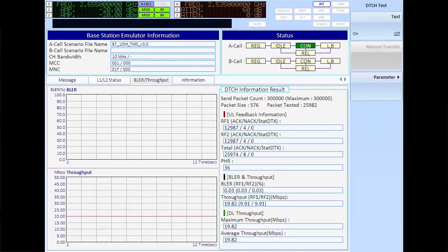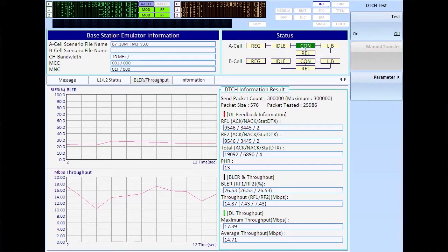The favored metric for determining if a MIMO device is good or not is throughput. With our existing call parameters set up on the PXT, the maximum throughput of this device is 19.82 megabits per second. We've lowered the cell power to a level where we are beginning to see some impact of the receiver sensitivity. As you can see, our throughput is slightly below the maximum rate. Now let's see what happens to our throughput rates when we start rotating the antenna pattern.